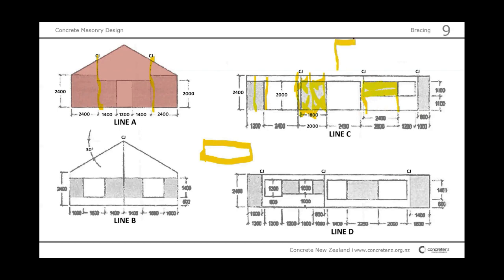Simply because if it's a standing panel, it can tilt over much more easily than a lying panel. So that's much better for bracing. This is how 4229 works. We only brace between the openings and the construction joints. So now we look at these panels.